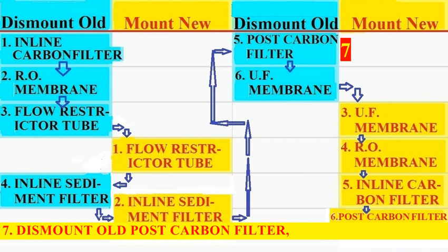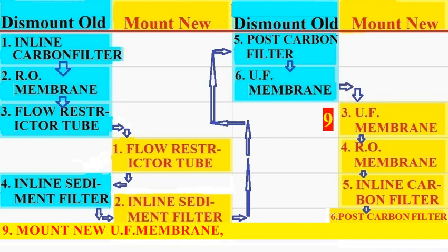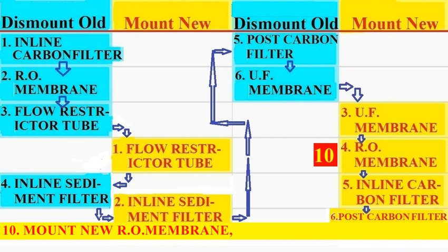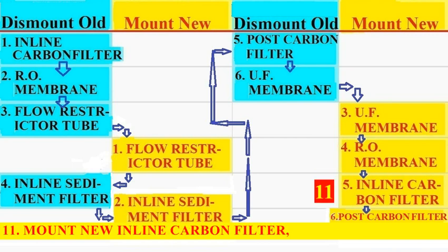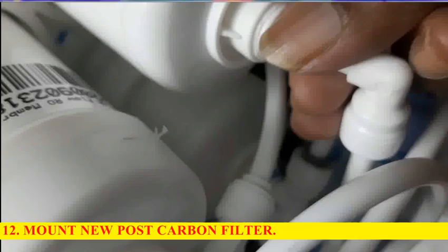7. Dismount old post-carbon filter. 8. Dismount old U.F membrane. 9. Mount new U.F membrane. 10. Mount new R.O membrane. 11. Mount new inline carbon filter. 12. Mount new post-carbon filter.